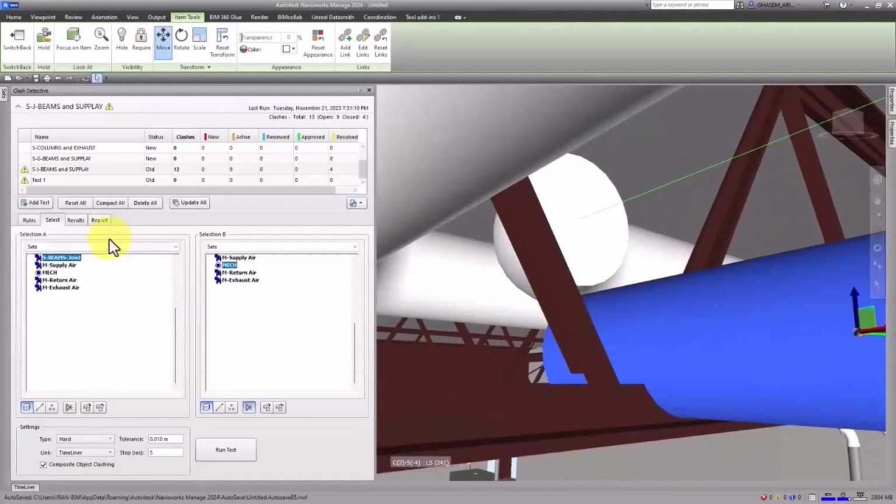In this situation, when you deselect this checkbox, the clash testing will be between this and this at first, and one more time between this one and this lower element. Or it's better to say we have an extra clash test. And in these situations, we should select this checkbox. And we need to define this as one clash, not two.